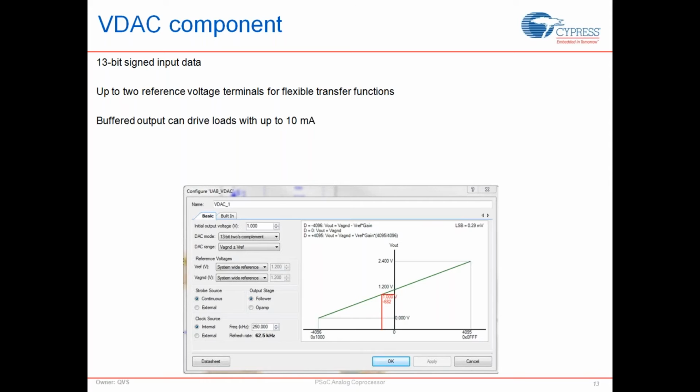You would typically use this kind of external clock configuration when you want to synchronize your VDAC with another digital system. Let's say you have a bunch of signal acquisition systems going on in the background, which are using the ADC and the sequencer, and you want to make sure your VDAC's outputs are getting synced using a DMA at a consistent rate.